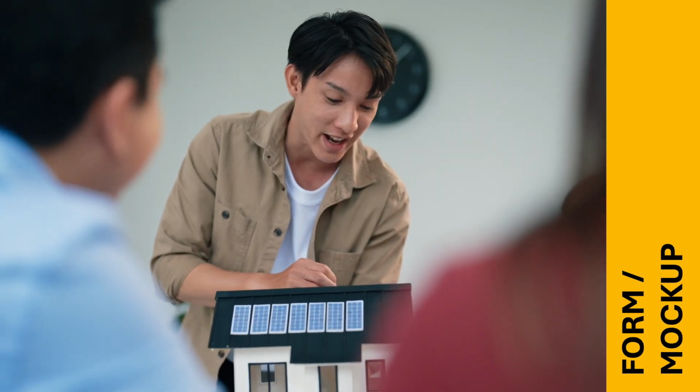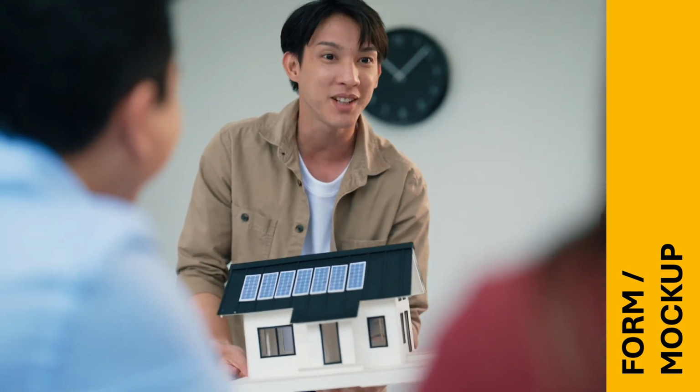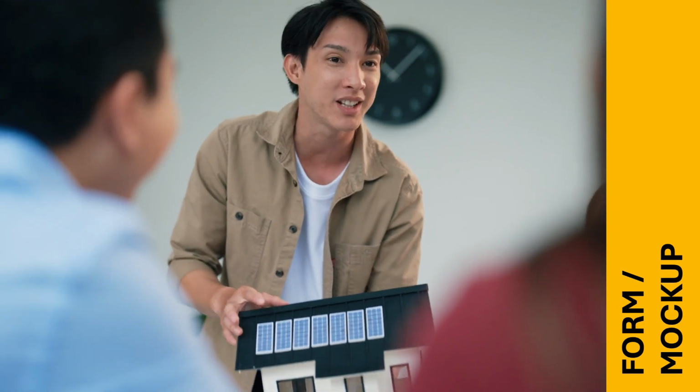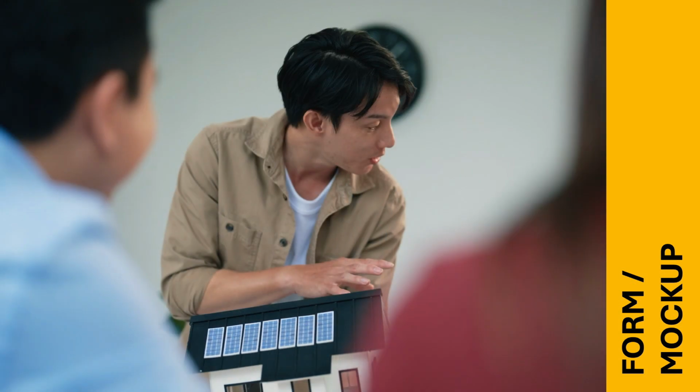Form prototypes, also known as mockups, focus on exploring the shape, size, and ergonomics of a product or system without necessarily addressing its functionality. To create a form prototype, it is important to use materials that represent the part of the form being explored. For example, if it is a digital product, using digital tools to create the prototype is most appropriate. If it is a 3D object, materials such as cardboard, foam, or 3D printing could be used, depending on the fidelity explored. Form prototypes allow exploration and assessment of physical attributes such as size, weight, and visual appearance.